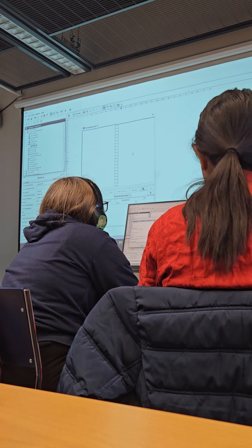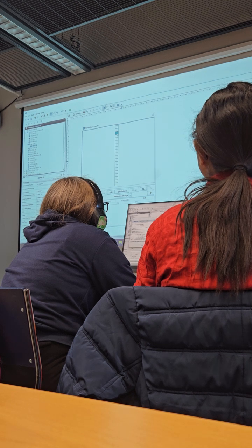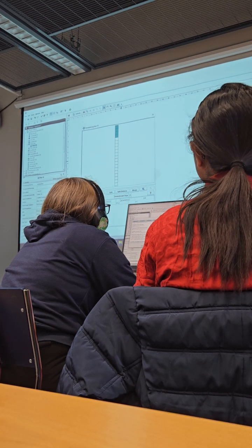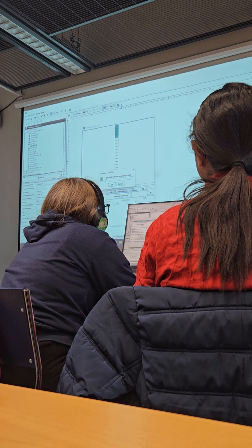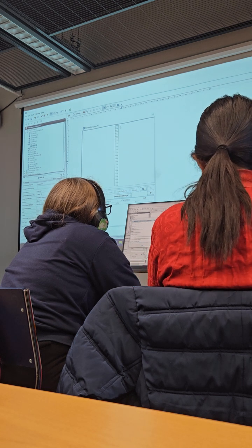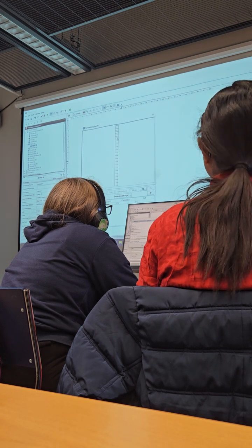Re-nodalization works in such a way that you just pick some of these nodes, and you can then, if you want, for example, split these 4 top nodes uniformly into 2. Then you can just do the split uniform and put 2 here. Then you can put more nodes there.